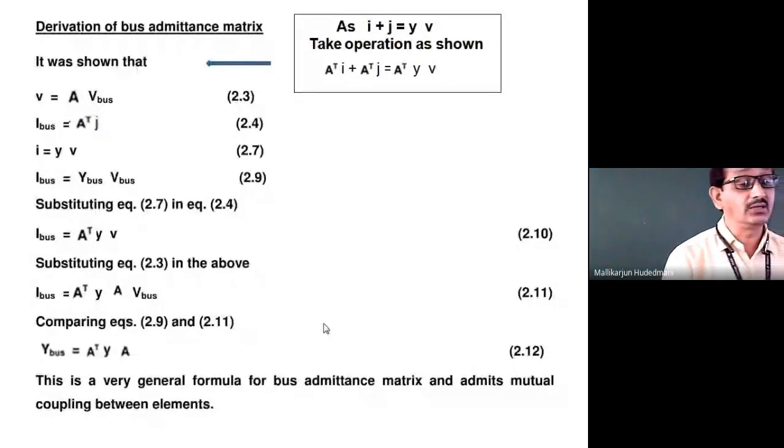Therefore, the A matrix is singular over here. The A matrix is nothing but one of the columns got eliminated from the all-incidence matrix that is serving as a base for us. So, that is singular. Hence, the transformation of elemental admittances and variables into a meaningful bus identity for the further calculation in the power system, this method we call the singular transformation method of Y bus.